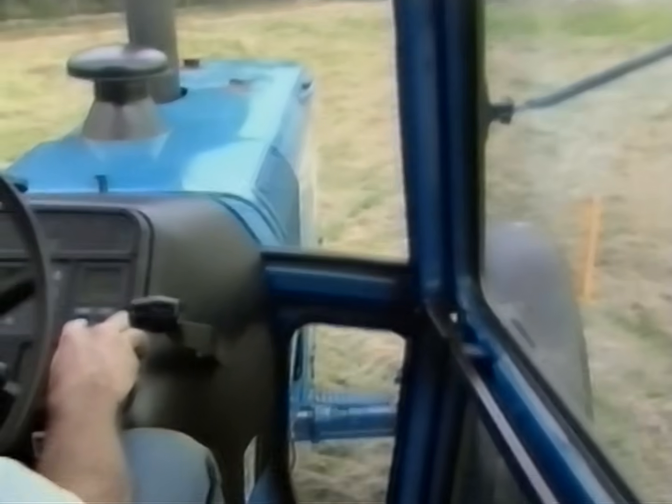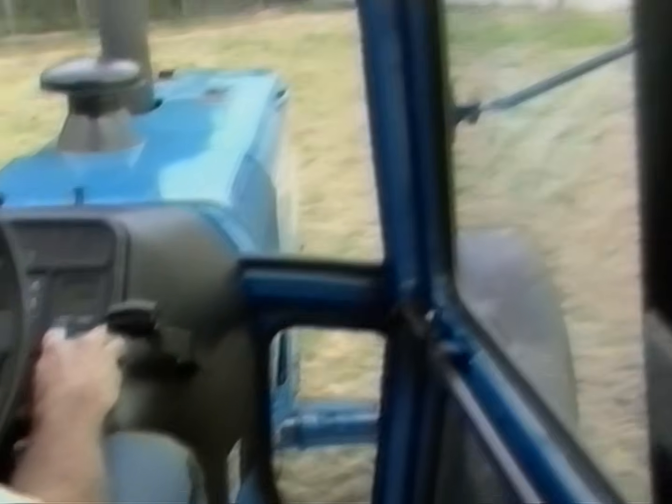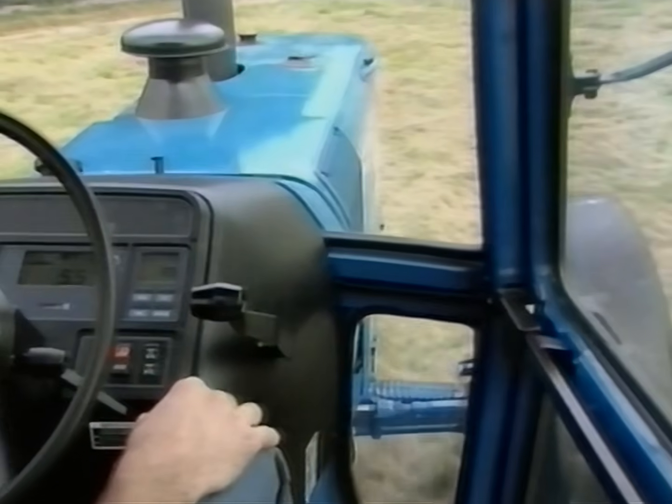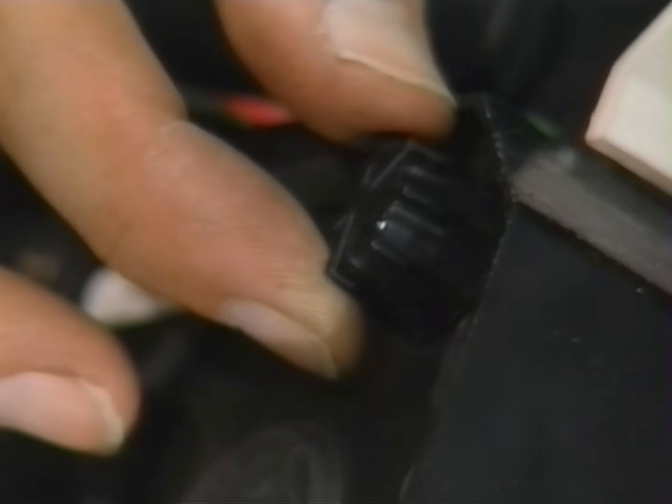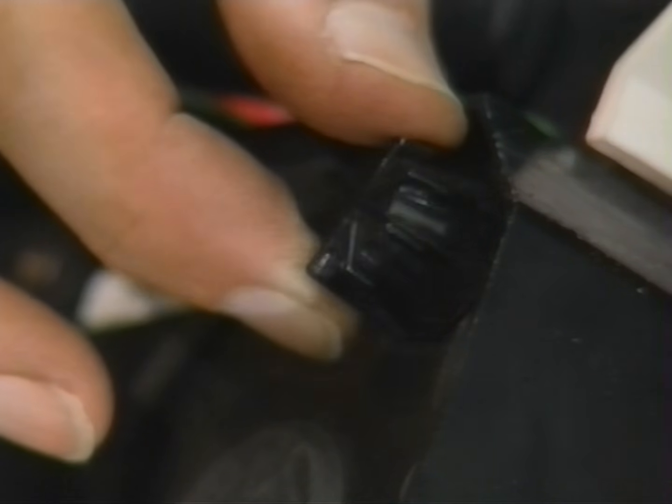As you pass the 400-foot marker, press the on/off switch again. At this point, the TPM displays the distance calibration number. On this TW tractor, the number is 86. After entering the distance calibration number, the next step in the setup is verifying the distance calibration. This simply means checking the distance calibration to make sure that it will result in accurate distance readings.